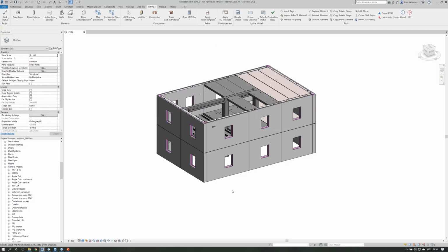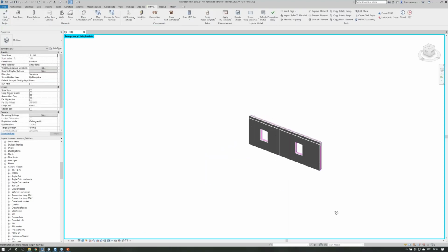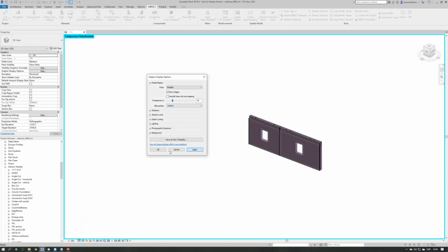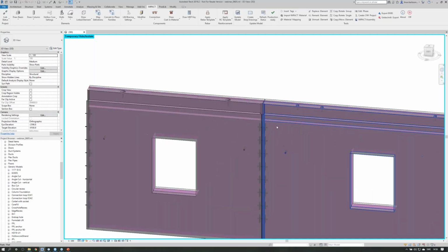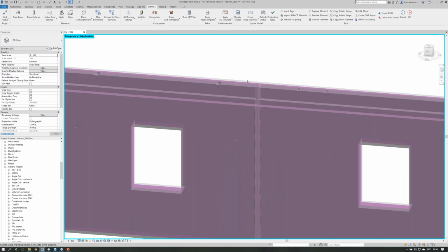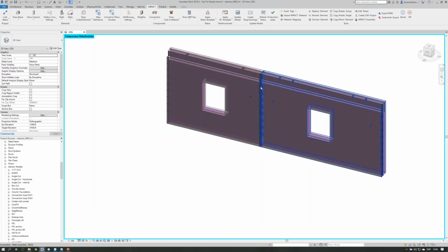Let's continue with the custom material templates that I talked about before. For you who didn't attend the first session, I can just quickly show you a little bit what we did. If I change the transparency a little bit, you see that when we divided the walls and we needed to apply the end caps to connect, we used something called joints to add some custom materials that will be used when we actually join the elements on the construction side.